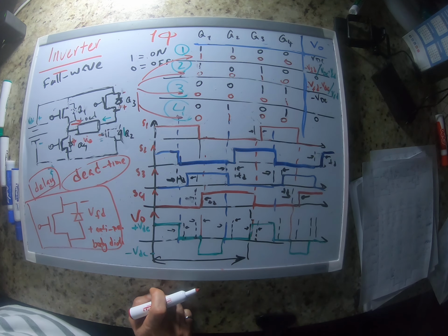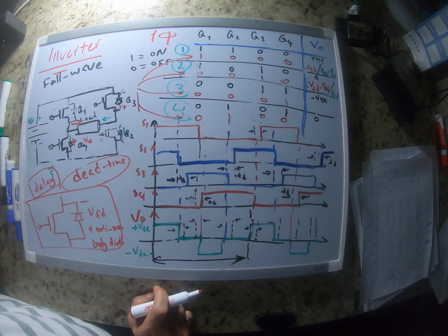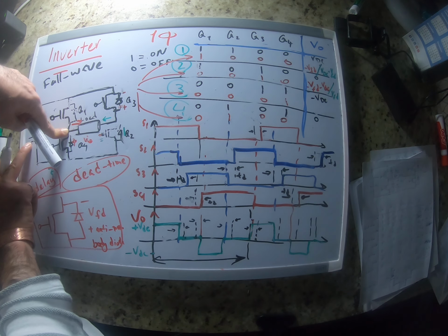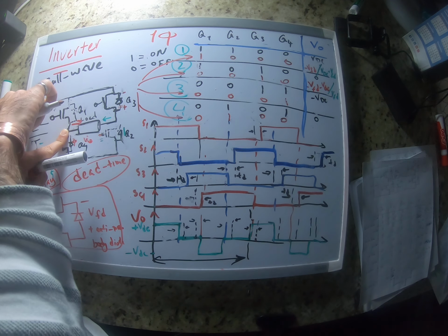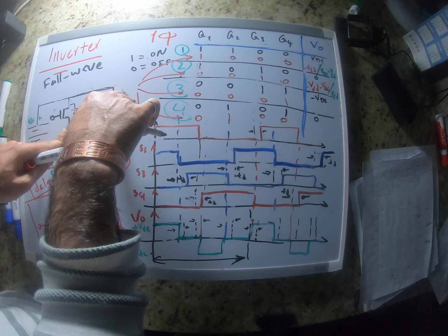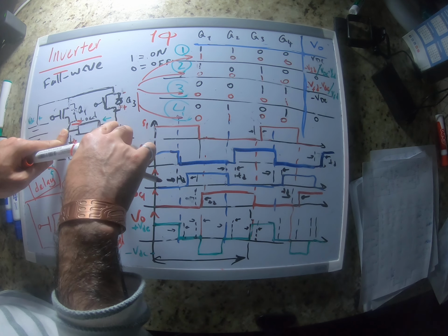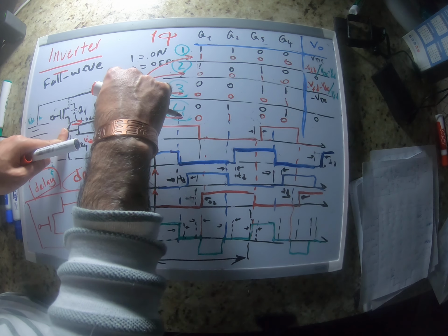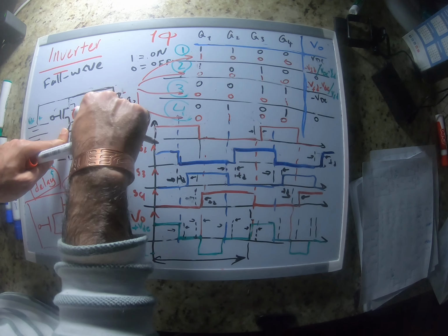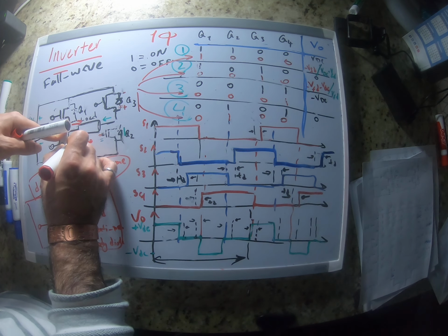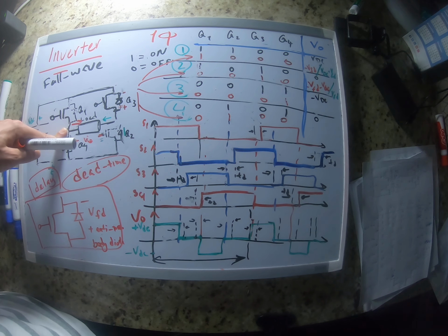Now, what's going to be the voltage across this load? This point is connected to the negative pin of the voltage. Here we have positive VDC. Here it's going to be positive VDC plus VFD, because we have the VFD voltage drop across the diode. The notation for our output voltage is like this.